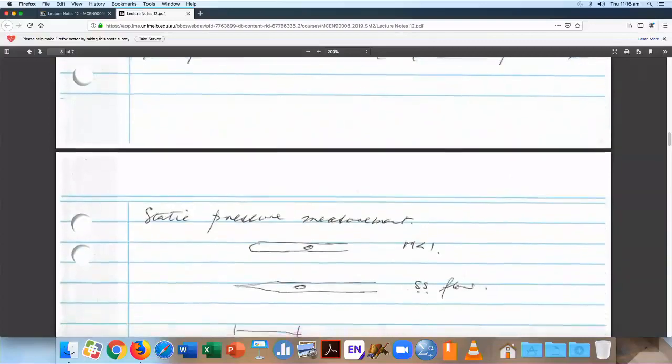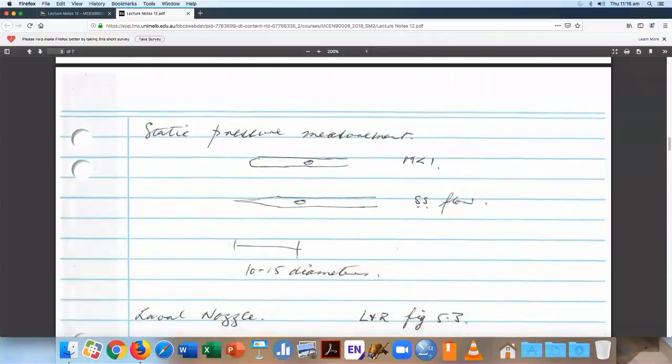And so how do we measure the static pressure? This is important. In subsonic flow, where we don't have any shock waves, we typically have a pitot tube, or pitot-static tube, in fact, which is a combination of a pitot tube which measures the stagnation pressure right here, and way down here you have some holes that go to a duct on the outside, and you typically have holes all the way around, and that is isolated from the tube inside, which is measuring the total pressure.